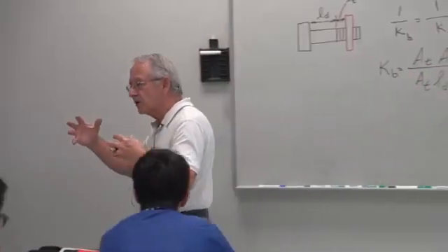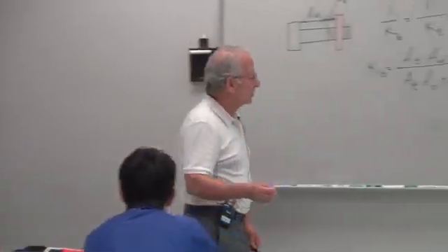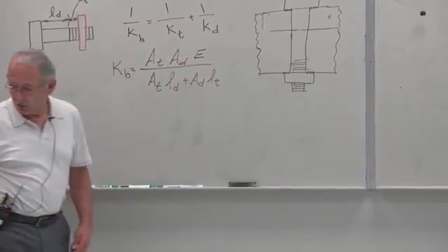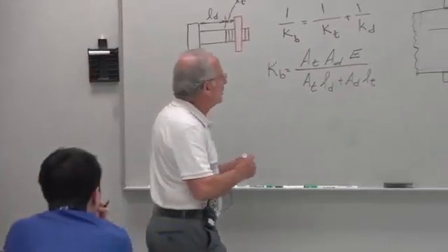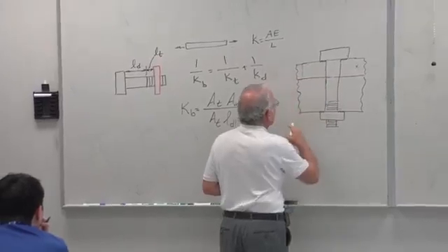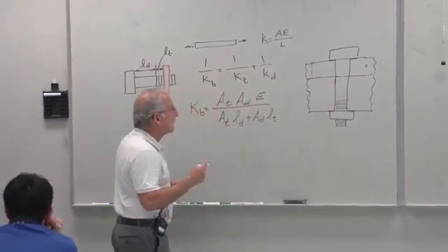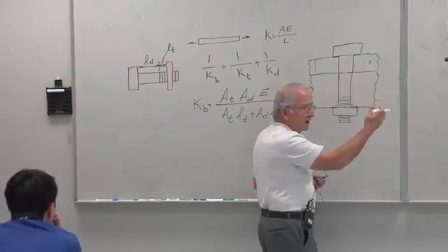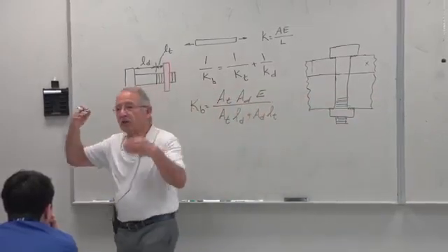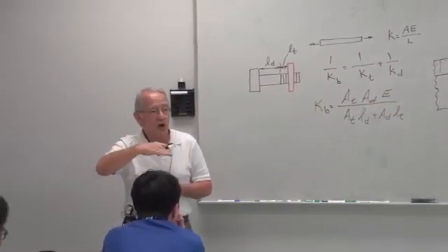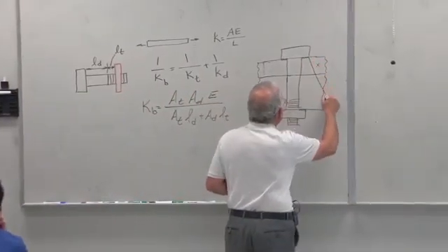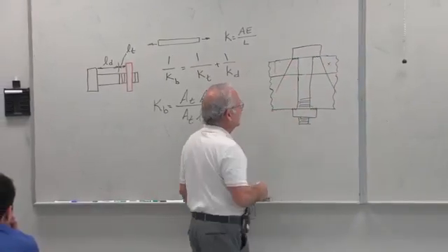So this load travels somewhat. Now, how much, that is really not quite well understood. But we have some approximations that we can make, and we can use those approximations to come up with a good design for a joint. So running some experiments and just simply putting strain gauges all over here, we find that this load is transferred from the underside of the bolt head to the top of the nut in a trapezoidal form, two-dimensionally, like that.